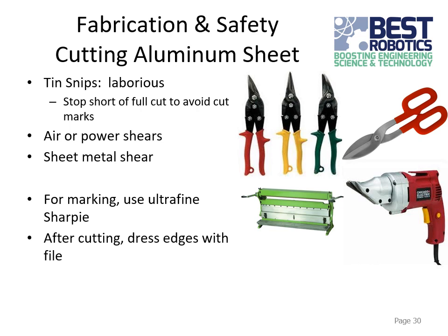And after you've cut it, and this goes for the previous things too, I should have mentioned, you want to clean up the edges. With the metal, you can use a metal file to clean up the edges so there aren't any sharp burrs on it. With things like plastic or wood or whatever else you're cutting, you can clean it up with a piece of sandpaper. And you can use some of that for metal too, to soften the corners a little bit. But a file works pretty well for cleaning up the metal edges.